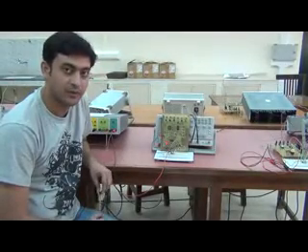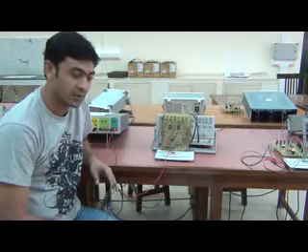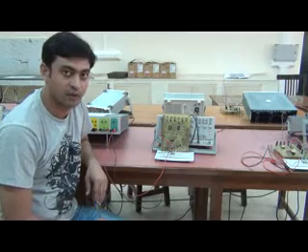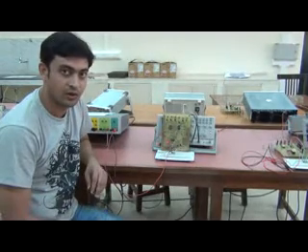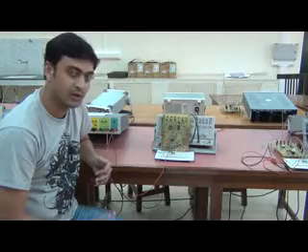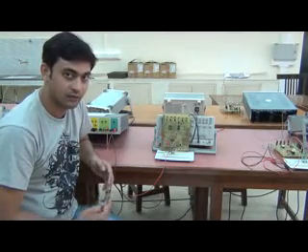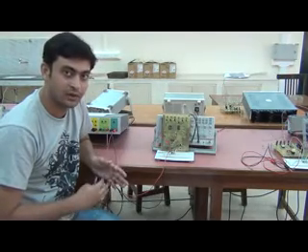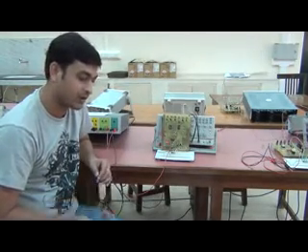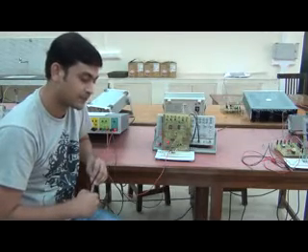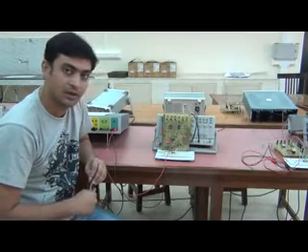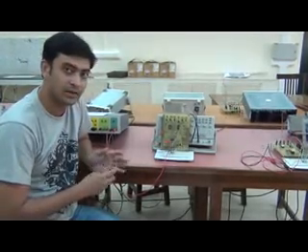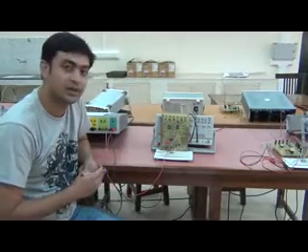So the first part of this experiment is to verify the operation of a JK flip-flop. A JK flip-flop is one of the basic flip-flops, which is driven by a clock, and based on the input conditions a set of output values can be observed. The truth table for this JK flip-flop is given at the back side of the handout. Currently we will demonstrate the truth table by making the circuitry on the breadboard and verifying the output on the digital test board.